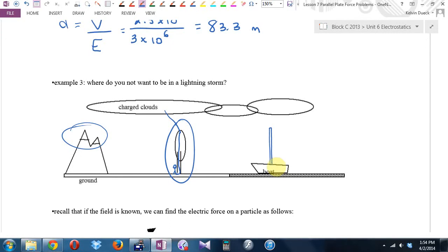Some people advocate clamping jumper cables to the mast and then trailing the jumper cables in the water. I don't think those jumper cables will provide a sufficient ground. I think they would get fried and you're still going to get shocked. Really, we don't get lightning storms on the West Coast the way they do down in Florida. But any sailors in Florida will tell you every half hour you're looking on the horizon, and if you see storm clouds on the horizon, you fire up your engine and you get out of there. No one wastes time with it. You don't even risk it.